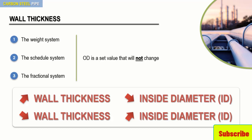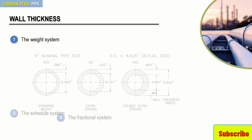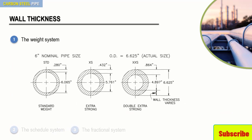An example of this variance in wall thickness is shown in the following figure. In this example, we are using the weight system. We have a 6-inch nominal pipe size, available in standard weight, extra strong, and double extra strong. Notice here that as we go from left to right, the wall thickness increases. Now, since the outside diameter for a given nominal pipe size is a constant, then as the wall thickness increases, it is the inside diameter that adjusts. And as you can see here, it decreases from left to right.